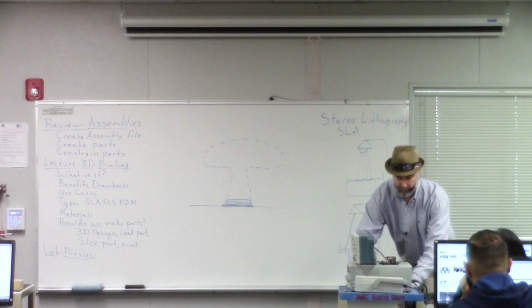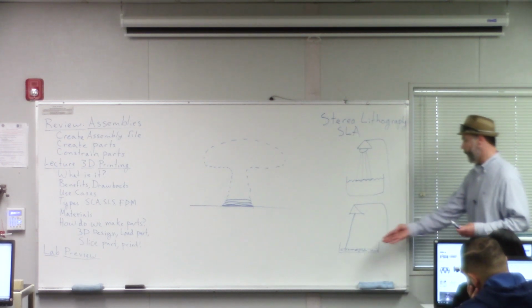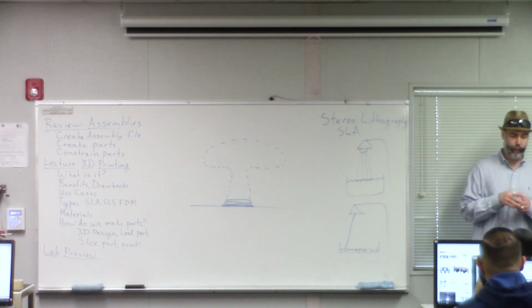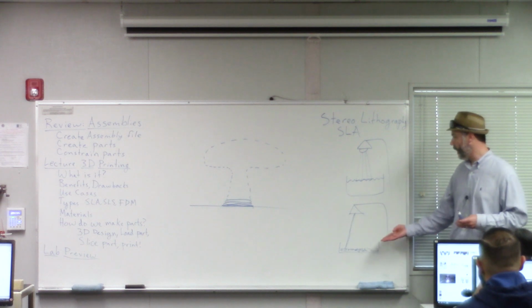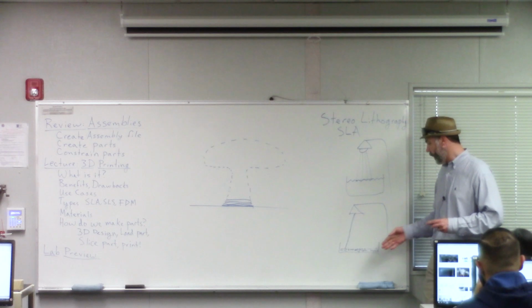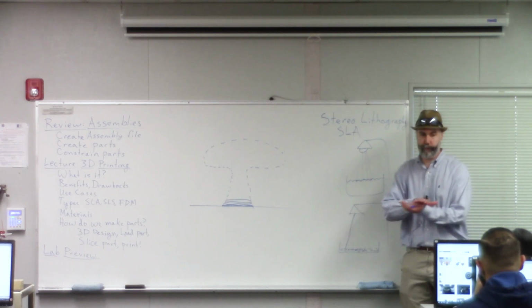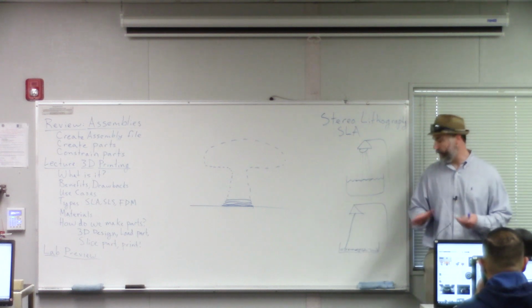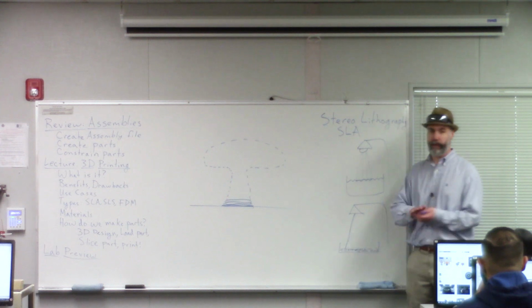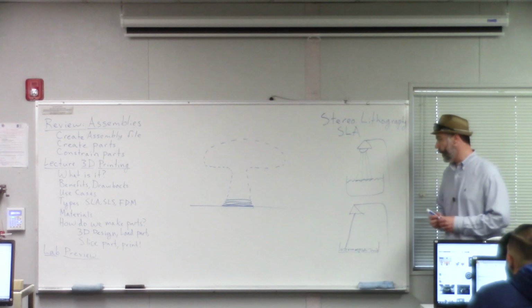Let me get this out of the way. So this laser beam melts the little beads down here, and they melt, and then they reform, they re-solidify into that first layer. And then typically there's some sort of a mechanism that pushes another very fine layer of dust over that first one, and then this laser beam comes down and melts that second layer, and so on, and it builds up parts that way, layer by layer again.